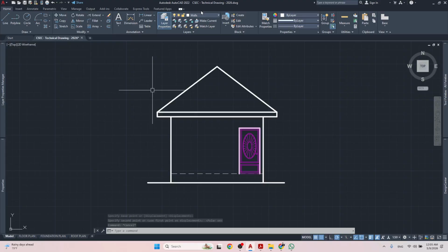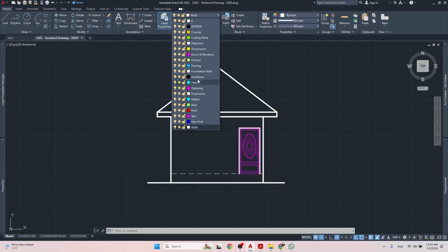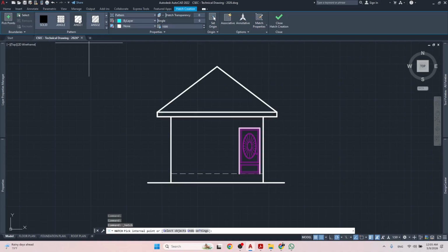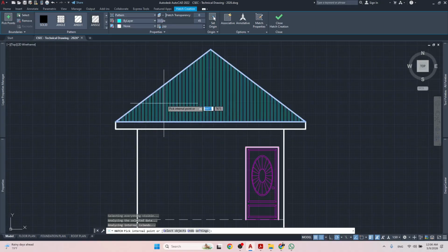And the next thing I would do is put a hatch in the roof. I'm going to use this. Actually, I'll use this one, but I'm going to make it a little bit closer, 500, maybe even closer than that, 250, right? And then I'm going to change the angle. Right now it is 45 degrees. So if I add 45 degrees more to that, it should straighten itself out to 90. 45 plus 45 is 90. Right, so there we have my galvanized pattern.